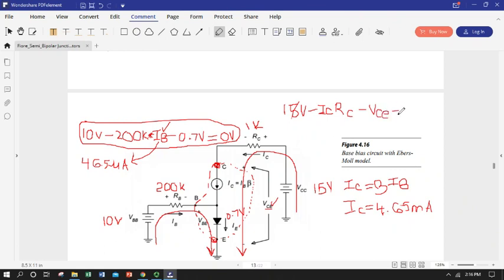And that's not a magic formula, that's just Kirchhoff's voltage law being applied from ground, raising voltage going through this supply, dropping voltage DC over a resistor, good old Ohm's law, and then saying, hey, I have to get back down to ground, so the remaining voltage that I didn't drop over here must be dropped over the transistor.